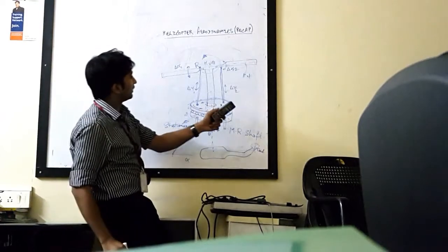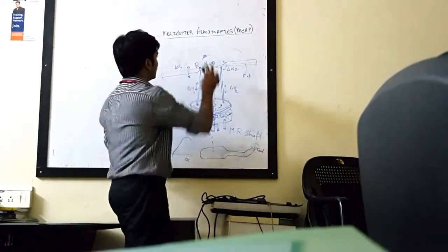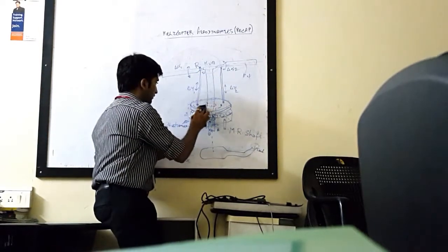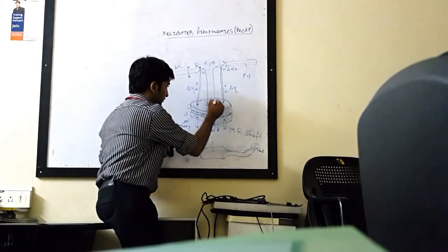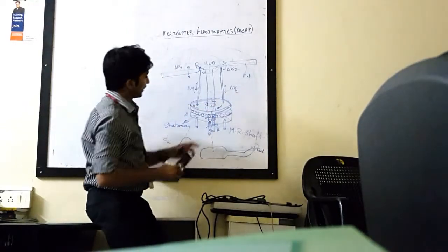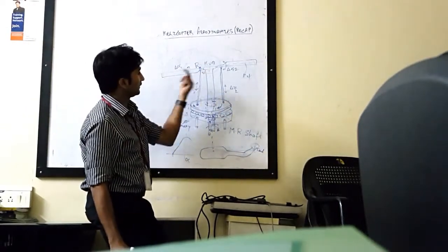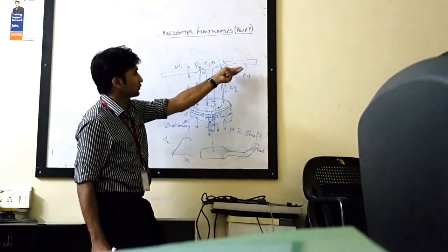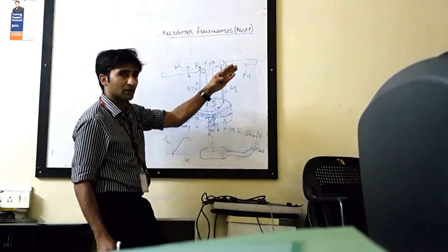So now the direction of rotation is this. You have the direction of rotation occurring like this, right? Now phi is defined with respect to this. When phi is 0, you should have maximum lift because you want to pitch down.